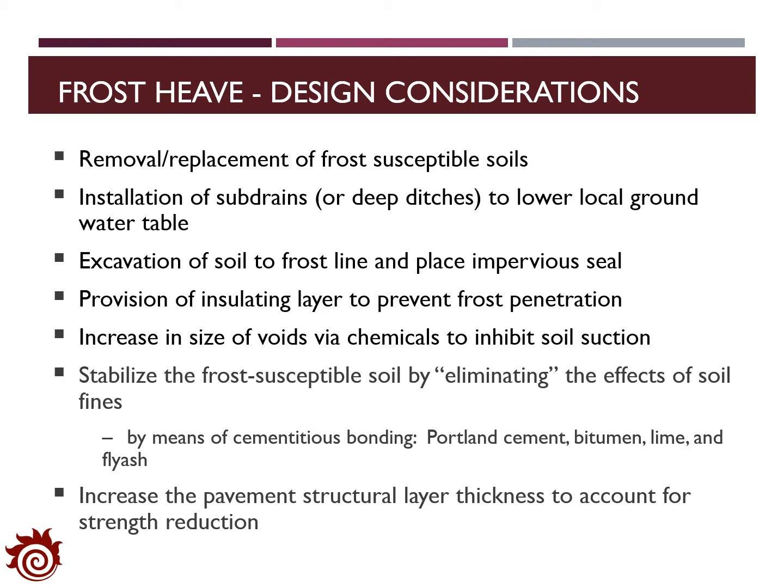In addition, we can stabilize the frost susceptible soil by eliminating the effect of the soil fines, such as introducing cementitious bonding with Portland cement, bitumen, lime, and fly ash. Finally, increasing the pavement structure layer thickness can also account for the stress reduction.